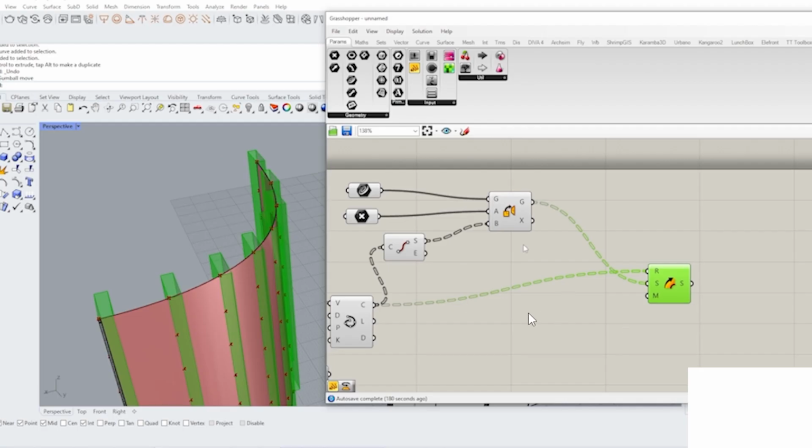As you can see here, the geometry is not rotating perpendicular to the surface at each given point. What we did initially was we took the curve and found those 2 endpoints, picked one of the endpoints, and that was our base. So it was giving us the proper base of the geometry, but it was taking the default X and Y as the orientation. So it oriented the geometry correctly and extruded that, but the plane defaulted to the default X and Y. Sorry, lots of words.